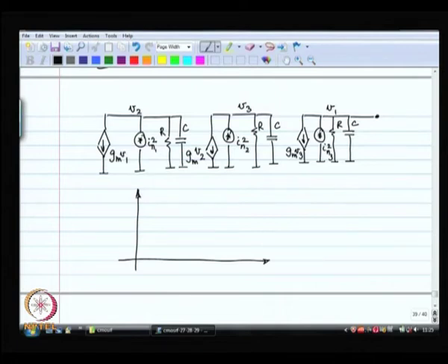If I have noise at DC, let us say I n is a DC noise current. So, that will create a V 2, that V 2 is going to create an amplified V 3, that V 3 is going to create an amplified V 1, right. The net result is going to be that I am going to get some noise at DC. Of course, at the desired frequency of oscillation, the noise is going to shoot up.